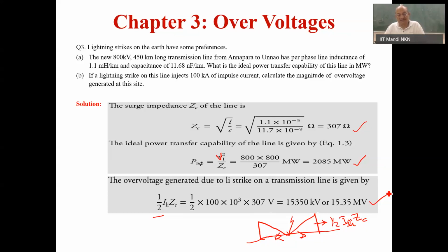And the traveling wave of such high voltage should be grounded as early as possible. The first place to ground is across the first insulator string. That is why we provide on every insulator string a kind of horn gap, two electrodes on either side of the insulator string, from high voltage towards the ground.